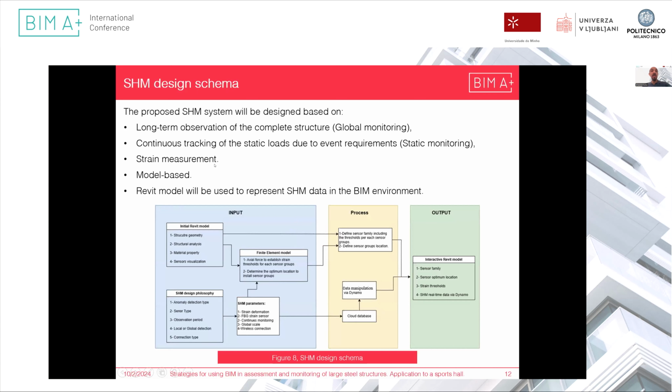Here, I have developed a simple schema so we can get an idea of what we will manage. But before that, we have been selected to monitor the building structure for long-term observation. It will be continuous tracking of static load, which is mainly due to the new load requirement for audio and video equipment. We will measure strain because, due to the characteristics of the building, it's hard to measure other things like deflection, which is what we did later on in the load test plan.